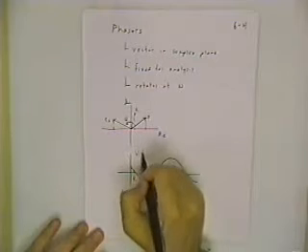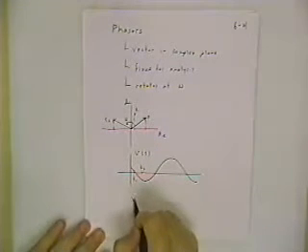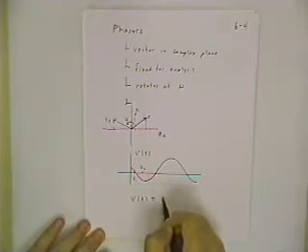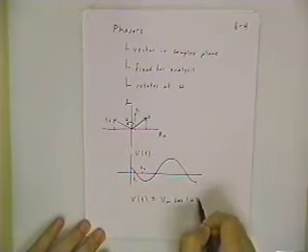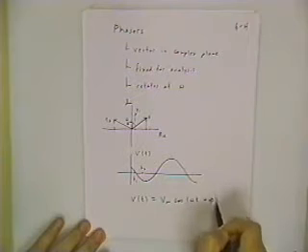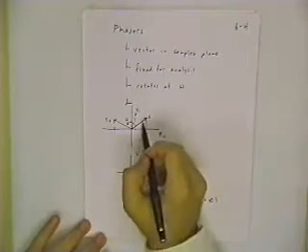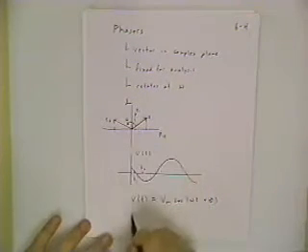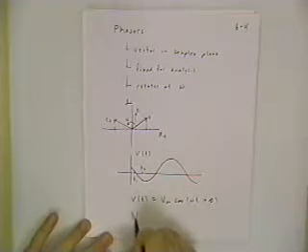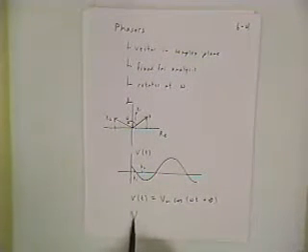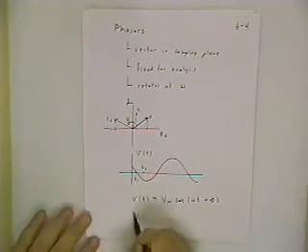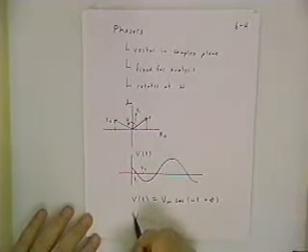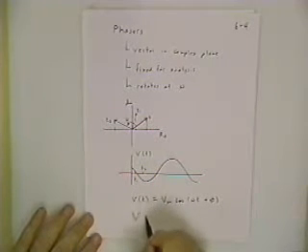Now if this is a voltage, and our voltage V of t is V magnitude cosine omega t plus phi, the way I write down this phasor, in handwriting, it's a bold-faced letter in text, and for a bold-faced handwritten letter you just do a double stroke for whatever is an appropriate part of the letter to double up. So for the voltage, it's this left-hand side.